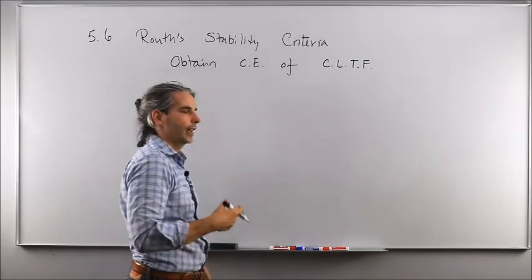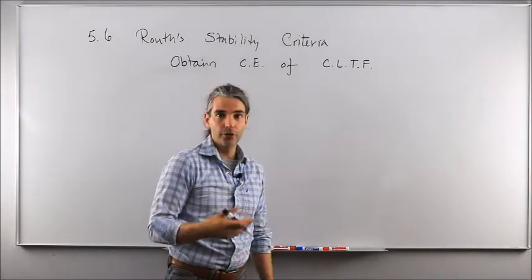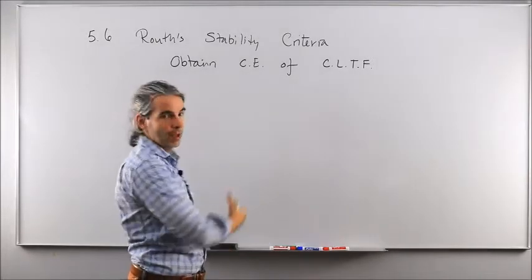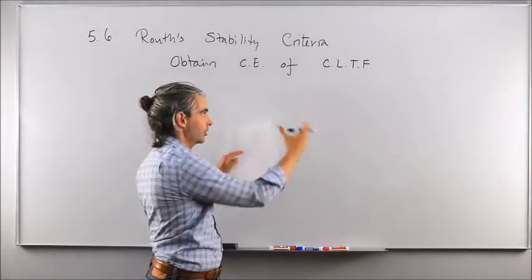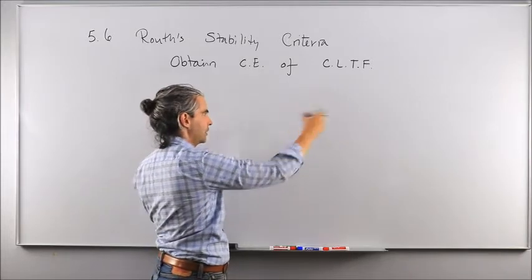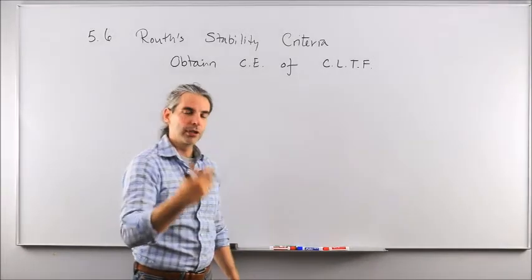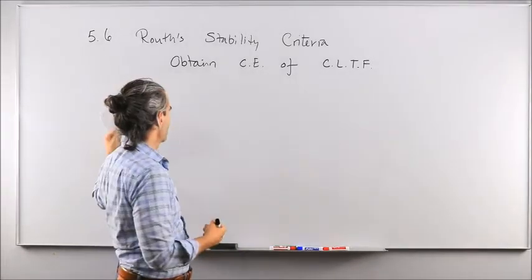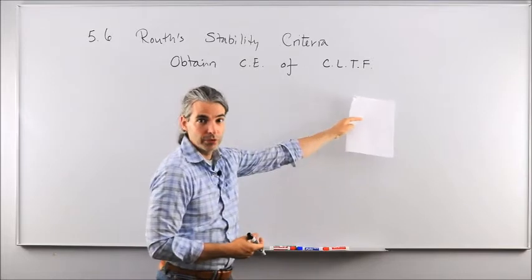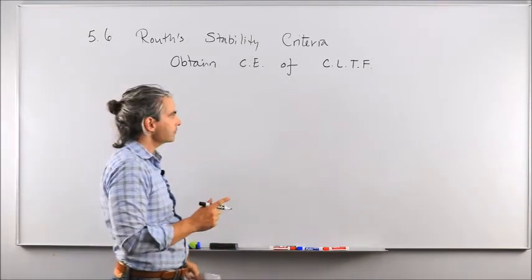Okay, so if that closed loop transfer function is not provided to you, you just look at the block diagram and merge all the blocks together, parallel configuration, feedback configuration, series configuration, and come up with the overall closed loop transfer function that relates the reference signal to the output of the plant by considering the feedback loop, okay?